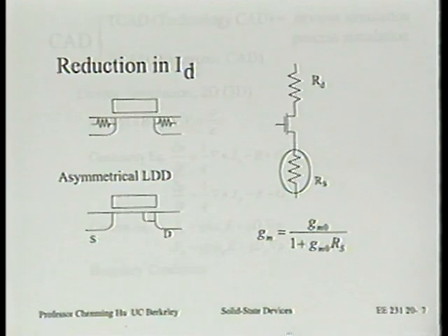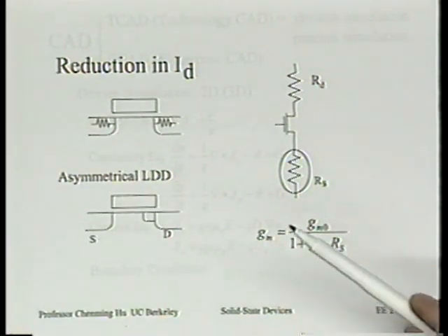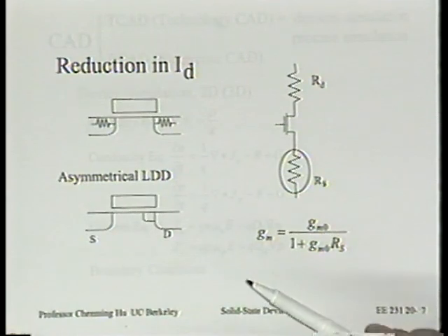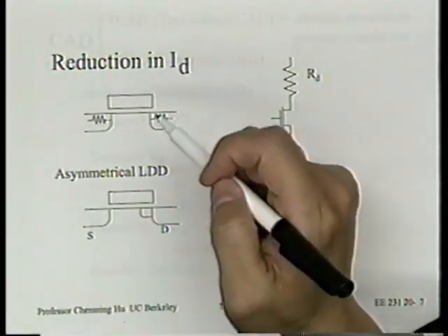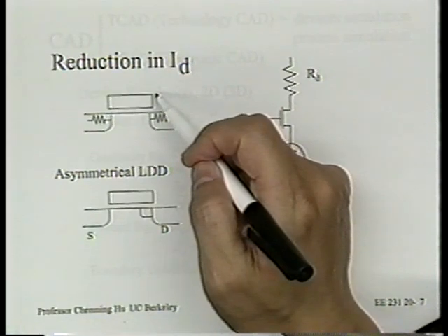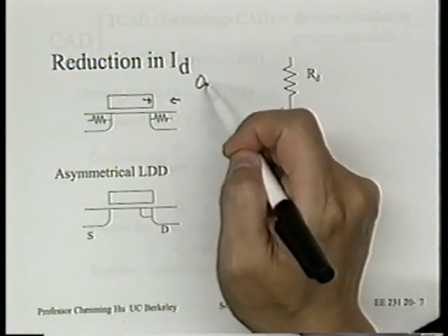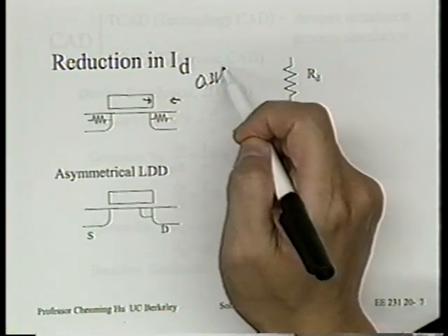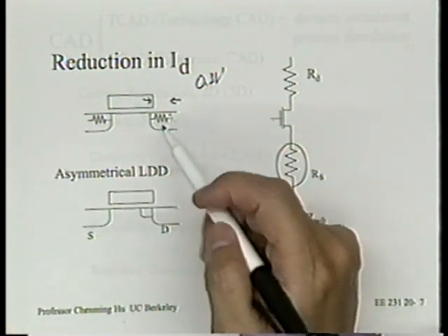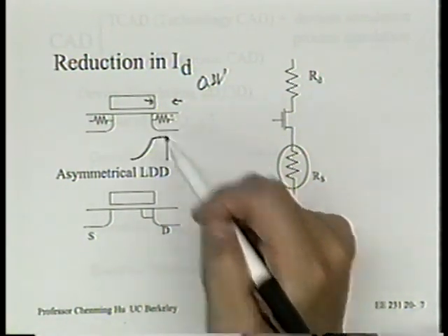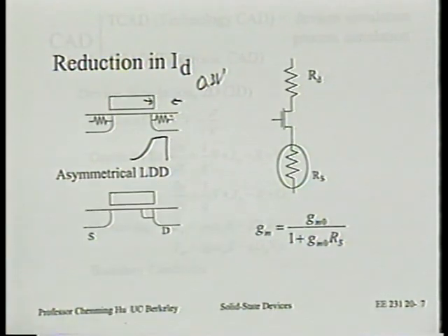So when you think about it, actually LDD is probably the best way to add resistors. So there are certainly things you can do. And by the way, I want to point out, adding a resistor and adding an LDD are still different in the following sense. This is the point Ryan was talking about. That is, the key to not using a lot of space, not a lot of length, to drop that 0.3 volt is to allow a very high electric field to exist in this extra area. And LDD does exactly that. We'll put a very high field, 5×10^5 volt per centimeter.